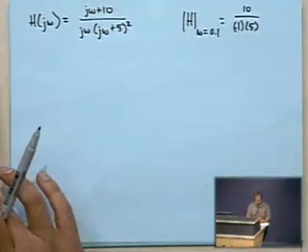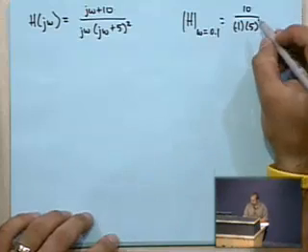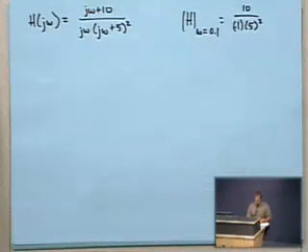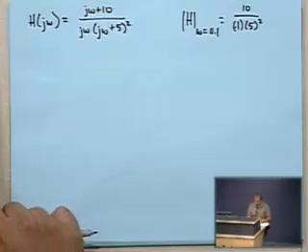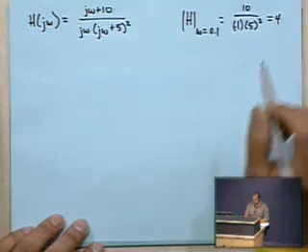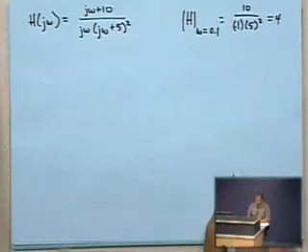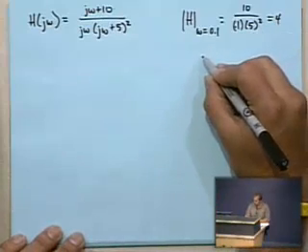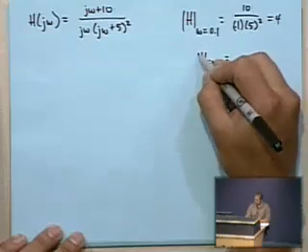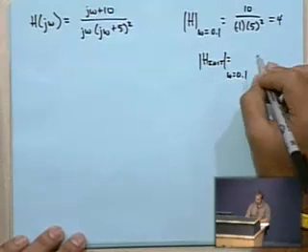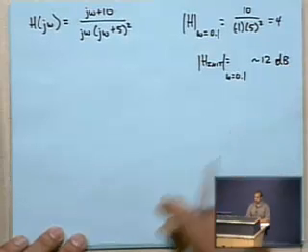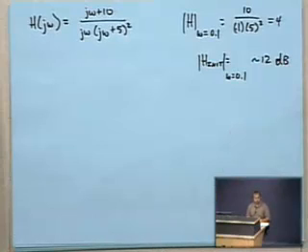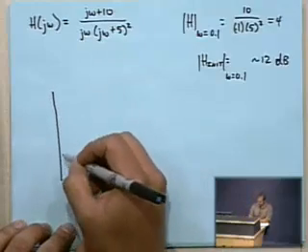So 10 divided by, what's that? Oh, yes, it is squared. Thank you. 0.1 times 25, that's 4. So 20 times the log of 4 is 12-ish. So the initial value as it crosses the line at 0.1 radians is going to be around 12 decibels. So something less than 20. Again, this is back of the envelope, let's not get too crazy about what we're trying to do here.